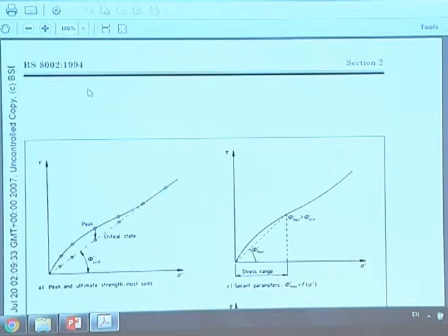You see this failure envelope over here. This failure envelope actually has a very interesting thing to it. It is a straight line over here. This is a classic failure envelope that Imperial College people would have plotted for soil. And that is that for lightly over-consolidated and normally consolidated clay, the failure envelope is actually a straight line. The reason is that when you have a soil that is slightly over-consolidated or normally consolidated, there's no peak strength. It just goes into the critical state. So what you are measuring then is the critical state line. This is part of the critical state line.